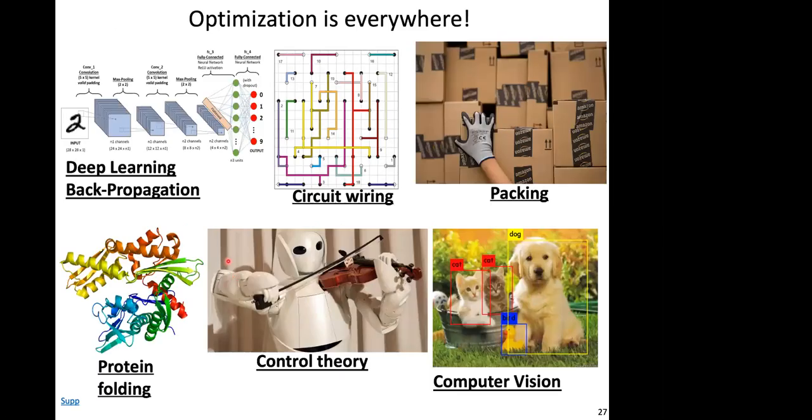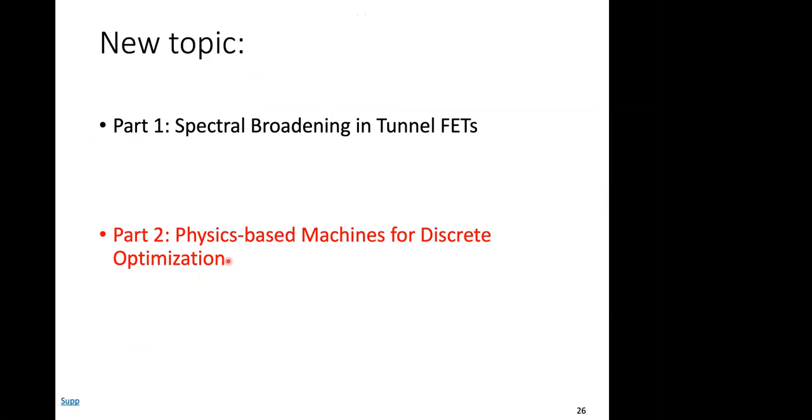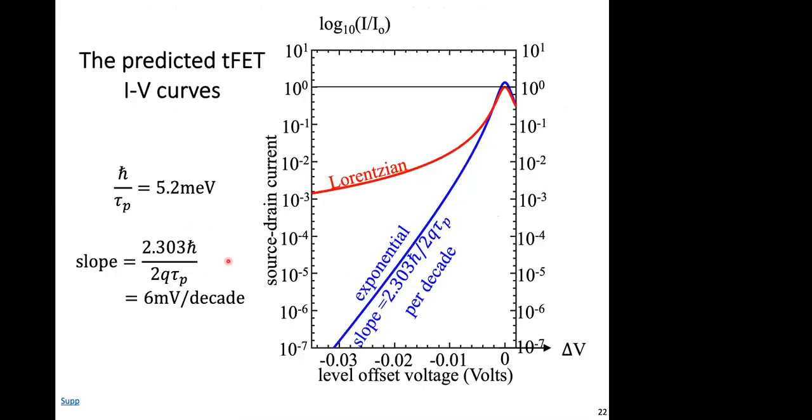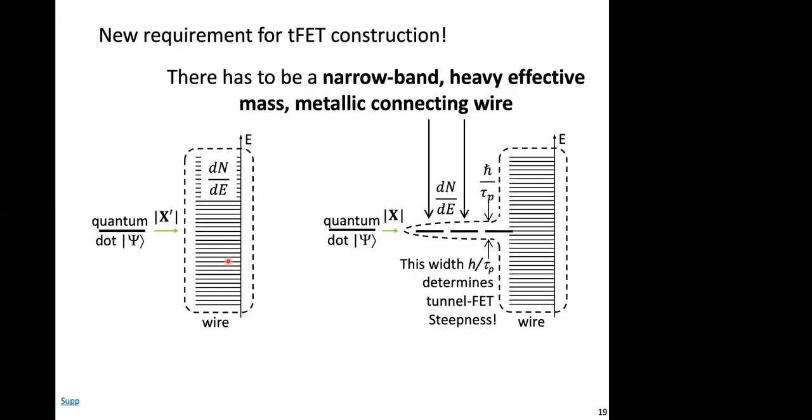I did have a question. I was wondering a couple of things about the nanowire, the nanotube. It is limited by the quantum conduction in one channel, right? So you're always going to have h over e squared resistance, or like 25 kiloohms. I wonder if you thought about that. The other thing is that none of this considers Coulomb blockade, and I was wondering how that comes into the calculus. It seems that would be important in a small quantum dot.